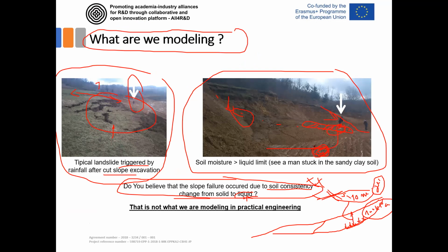If the material is better, it has better strength parameters, that means that the slope of this line is bigger than before, or this value of cohesion is higher than it was before the soil became liquid.